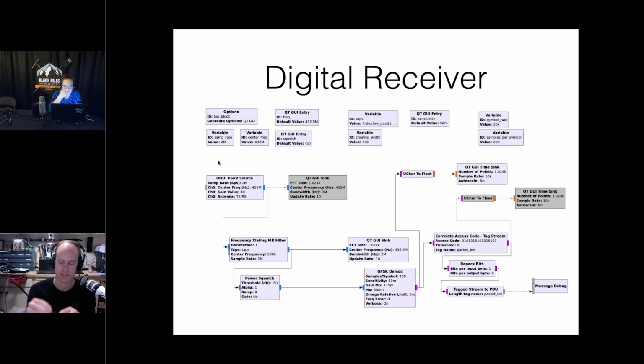And one of the things that you can do is jam the 315 megahertz band where they're trying to operate, such that they can't get into their car. Now, there are reasons why you want to do that, and some man-in-the-middle stuff that makes that useful. But you do that basically just by transmitting a simple tone that doesn't really do anything. It's just a basic signal with no data or anything in it at right about 315 megahertz, and the key fob won't work.